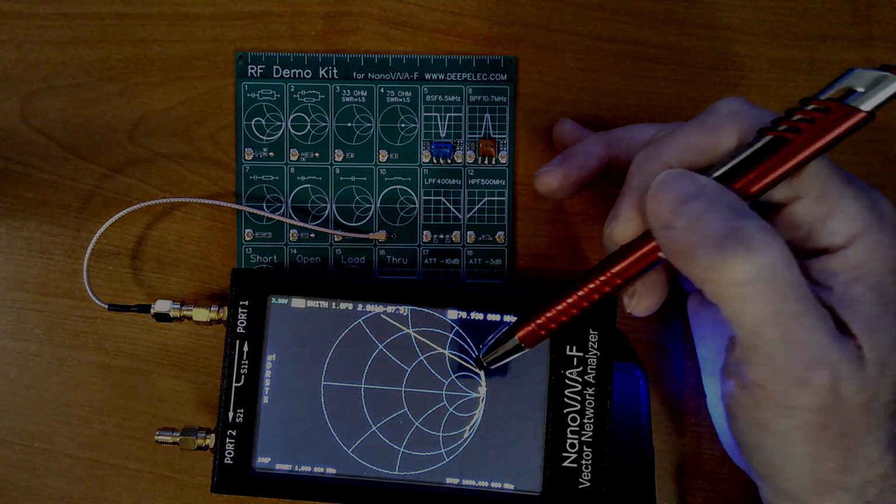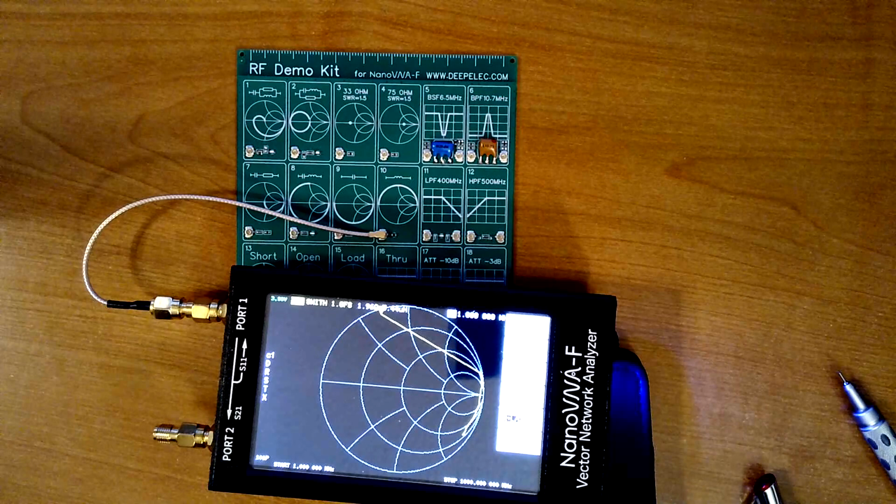and it simply, in the software inside the unit, drew a straight line. To read out the value with the NanoVNA, you need to set the Smith value to read R plus L or C. I've done that. You also need to run to the lowest frequency so that you're over on this side of the Smith chart. You don't want to be over here. And so I've done that at 1 megahertz, and it's reading 5.4 microhenries. So that's the base inductance of this thing.